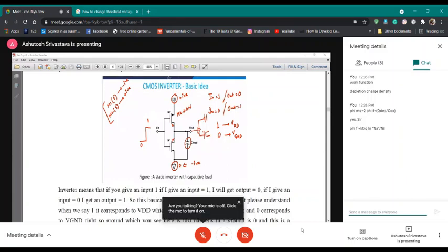Remember, the transistor threshold voltage is the voltage beyond which your transistor gets into the conducting state. Below the threshold voltage, the transistor is in the off state or the subthreshold stage, where there is still a conduction of current, but that is around 3 orders of magnitude lower than the normal conduction.